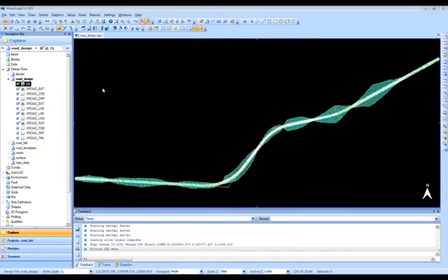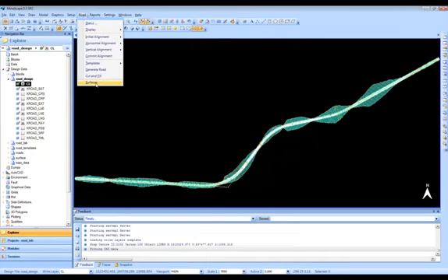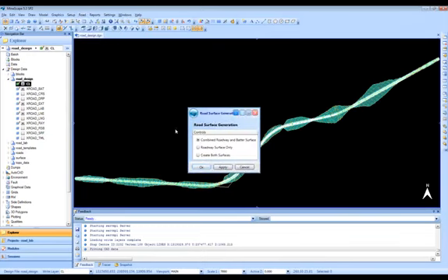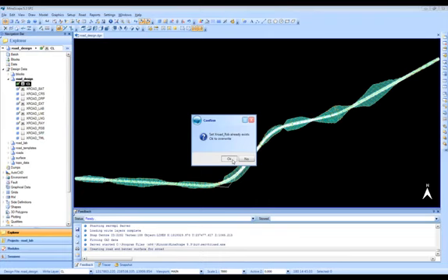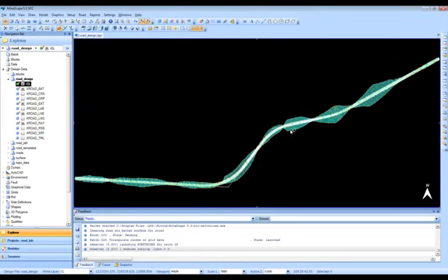And now that I've got my projections created, completed, I can then generate surfaces. So this really generates a triangulated surface. You can do a combined road and batter surface, or just a roadway only, or create both, but I'm going to do them all. Say OK to that. So basically it's going to take these design lines, projections and so on, and generate a triangulated surface from it. And here it has completed it.